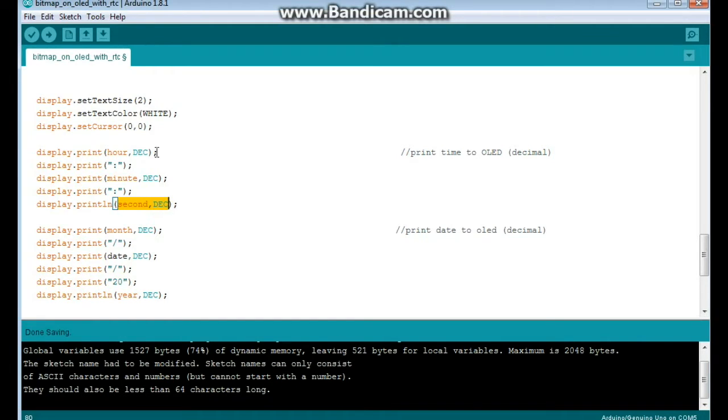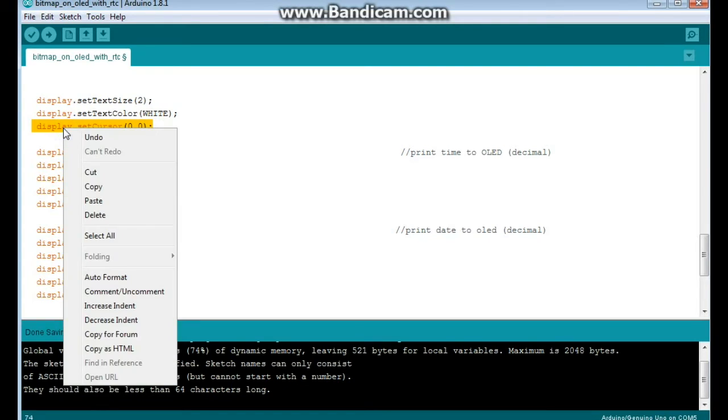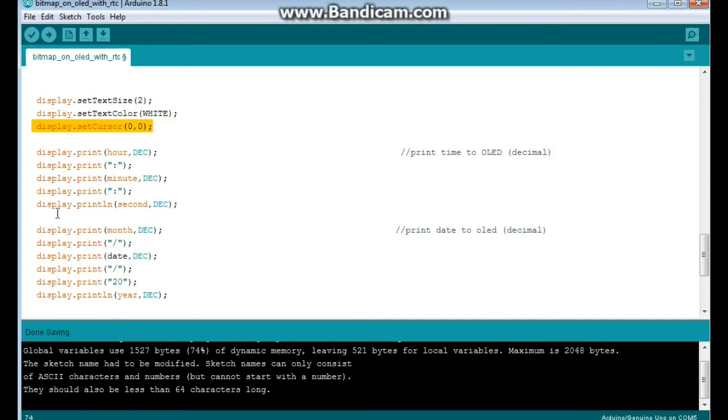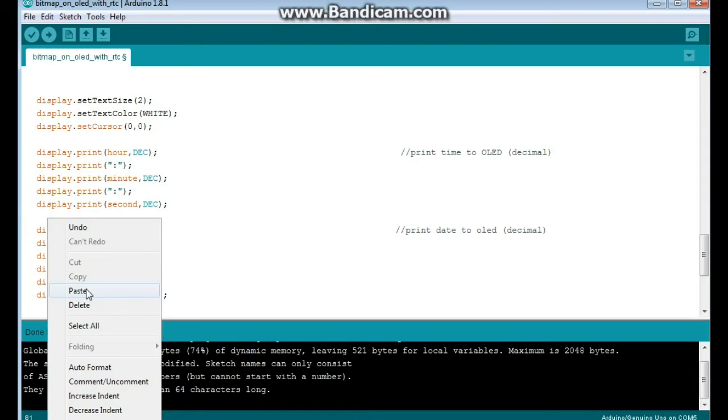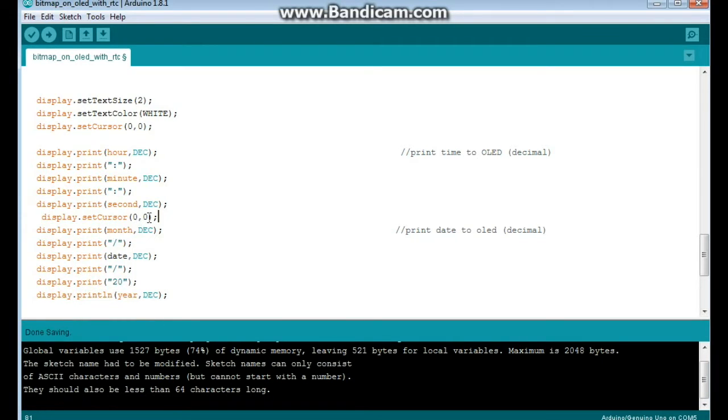Now, if you're using the standard font here, I believe it is like 7 pixels high. So if you wanted to just use display print commands, when you wanted to come down to the next line, you could come down here, say this is just a display print, put this in here and say X position 0 and Y position 8.